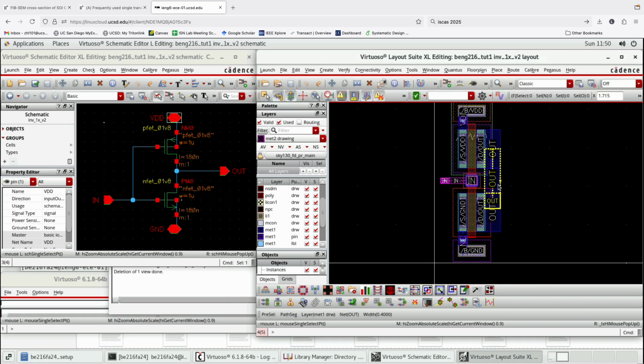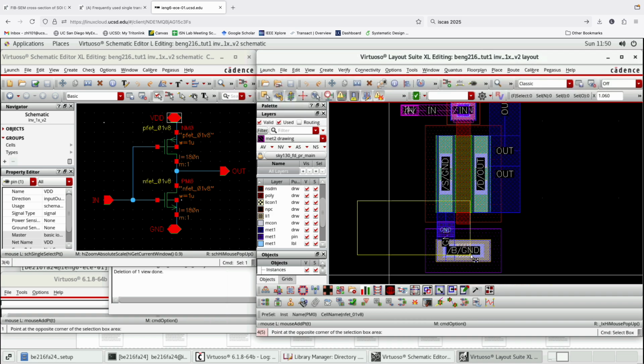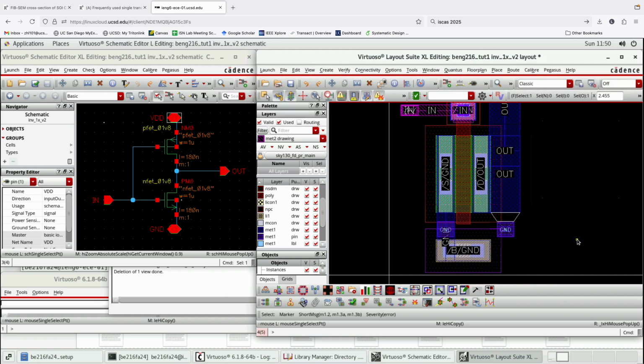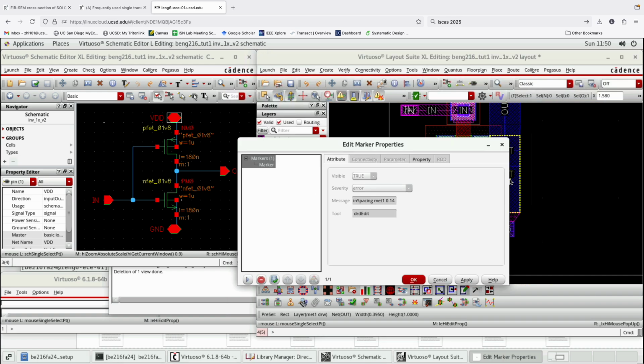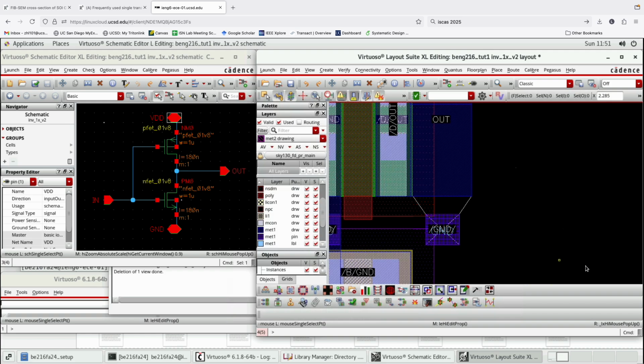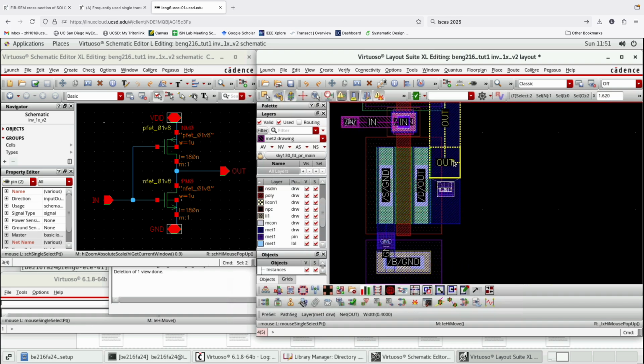Okay, last thing is the out, which I can also just copy this guy, copy, and you see, some of these markings are also very self-explanatory. This says min spacing metal 1.14. So this basically shows me a violation. This is why we want to turn these 2 guys on. Okay, so let's just copy this. Or sorry, now that I've just copied this, let me move this on top. Right, anywhere on this is fine.